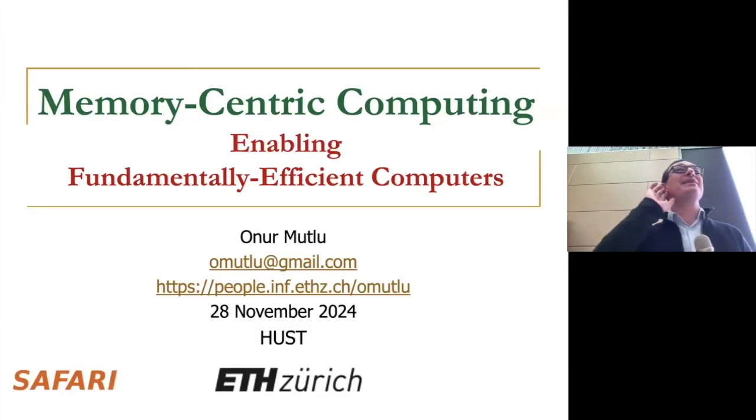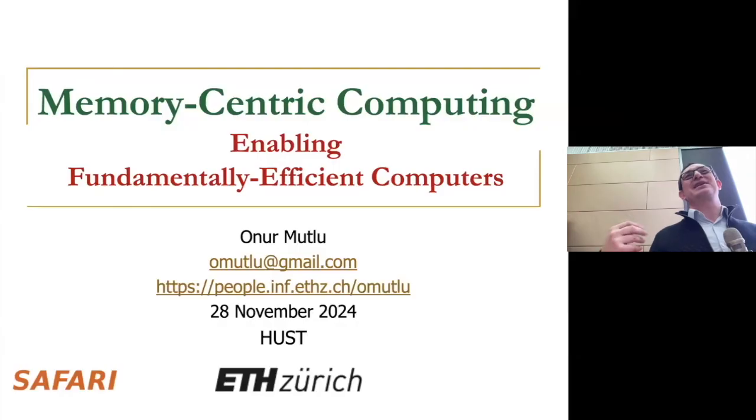Memory needs to do what? I mean, certainly, for example, my cell phone is consuming power doing refresh right now, right? Self-refresh. That's true, assuming it's DRAM. Refresh does consume power, but if you add computation capability, you will have a lot more power on the memory. Even with processing using memory, if you actually use all those memory cells to do computation, that will increase the power consumption. And you will need to increase the power requirements.